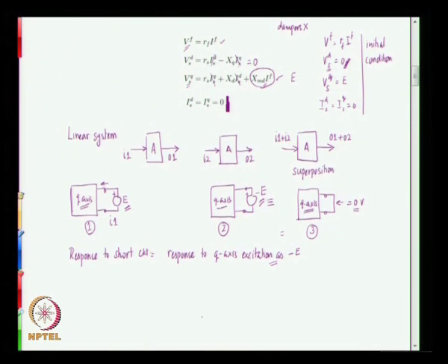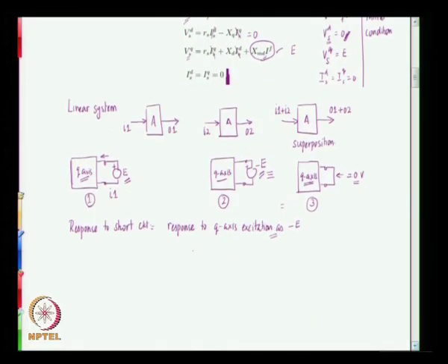However, in the alternator, the alternator is analyzed such that the flow of alternator stator currents is out of the stator, but all along right from the beginning we have been following the convention that the direction of current is taken to be flowing into the machine, and therefore, what we will get by this analysis is really current that is flowing into the machine, and therefore, if we want current flowing out of the machine, we simply have to take the negative of whatever current that we are going to end up with. So, this is what we are going to do,